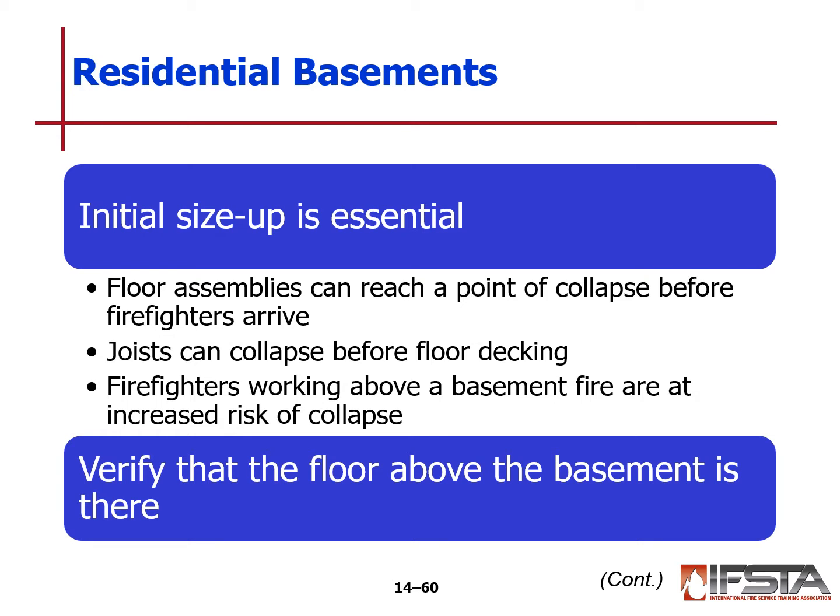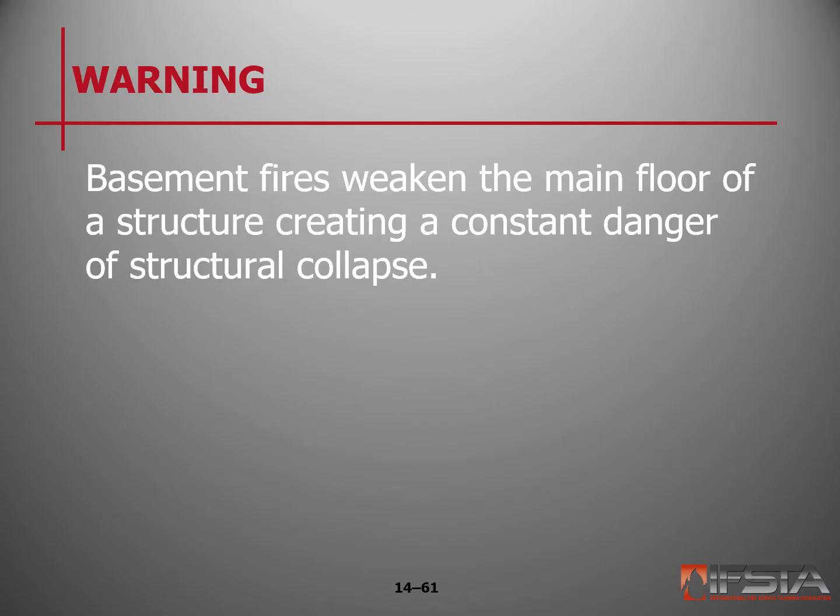You can have basement fires that go into a smoldering phase and they have burned out certain areas of the floor, as an example, and weakened that. And when you add the weight of 2, 3 firefighters and a hose line, you can collapse through it. Again, basement fires can weaken the main floor and create a constant danger of the collapse of the floor.